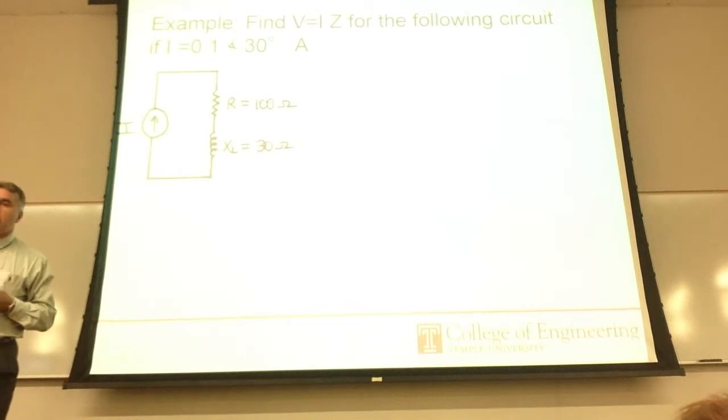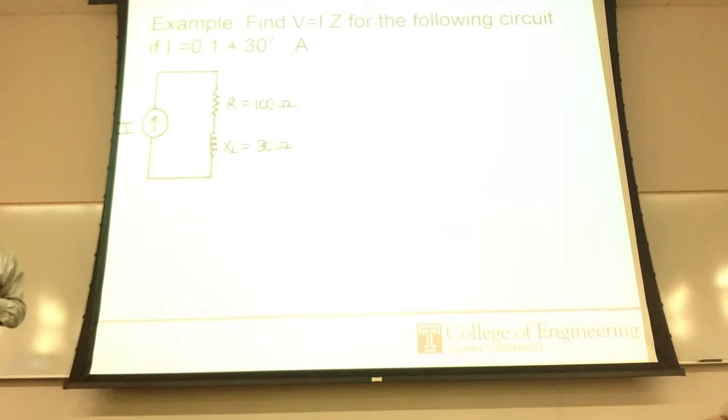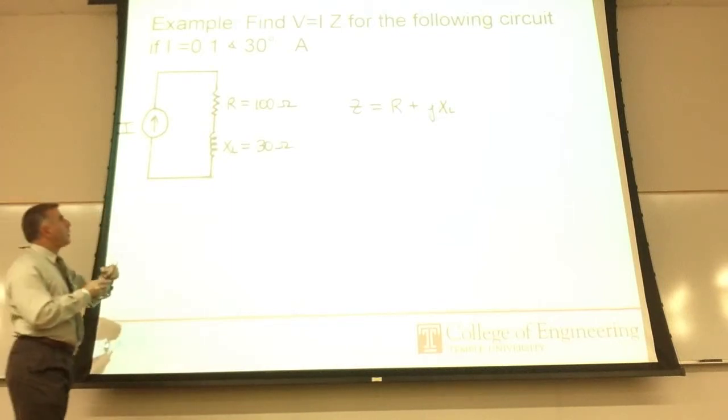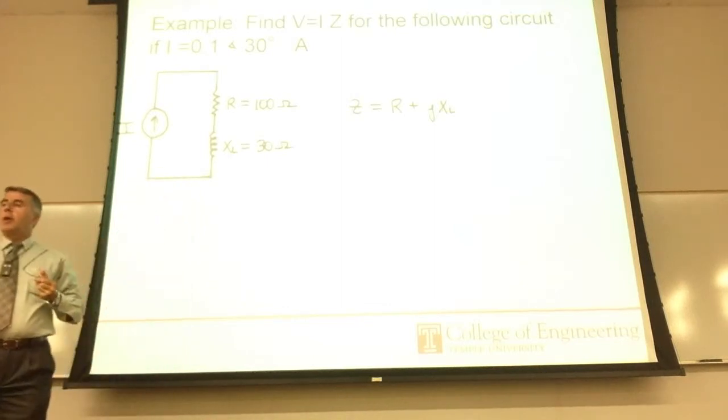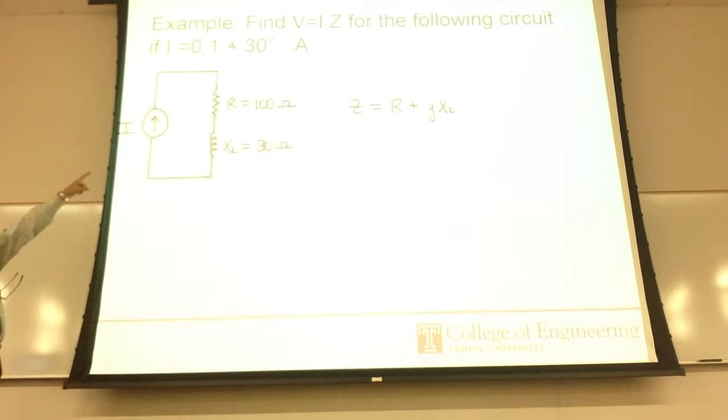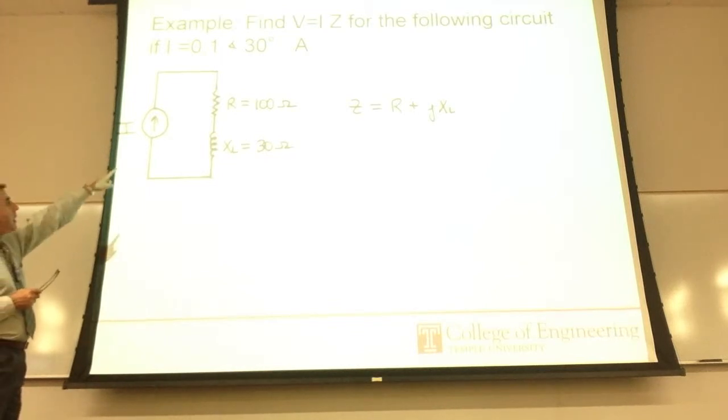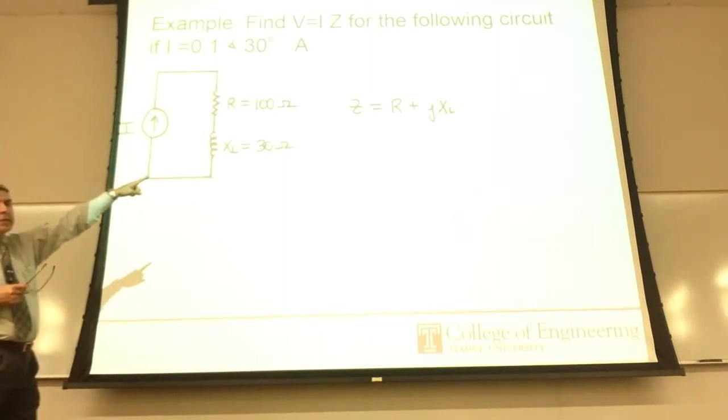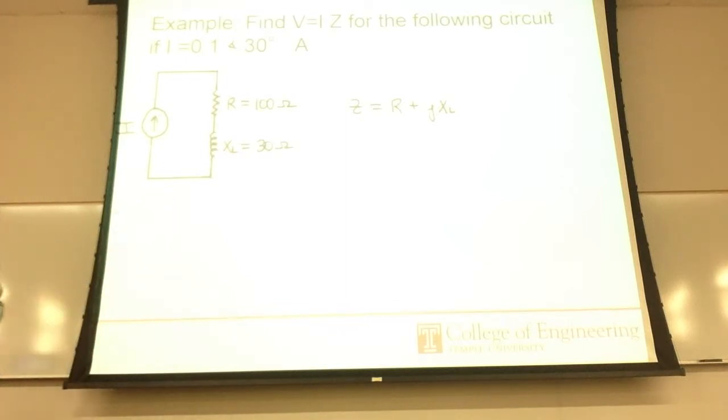What do we call that voltage law? Kirchhoff's law. That's right, Kirchhoff's law. Did we see that anywhere in my lectures? Yeah, I think that was the first session, right? So in this case, what we need to do is find, first of all, the equivalent impedance. Now, we have a resistor, and we have, what do we call this guy? The coil, what was it called? Inductor, right. We had a resistor and an inductor. For the inductor, basically the impedance is the resistor plus jXL, right? And in this case, it is simply 30j ohm.